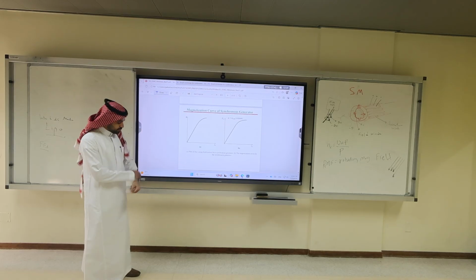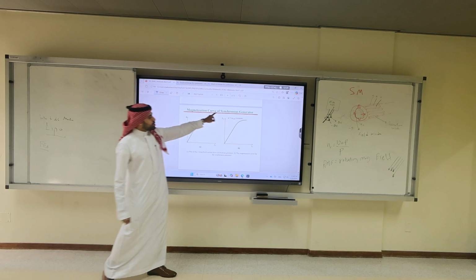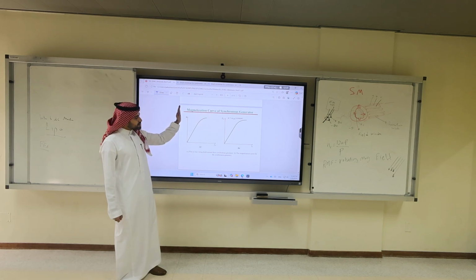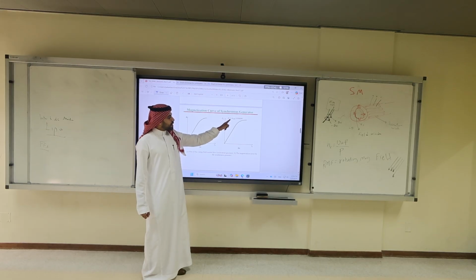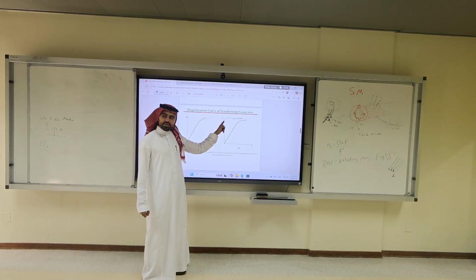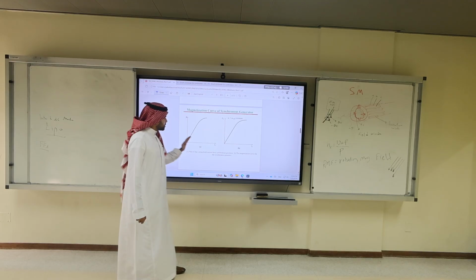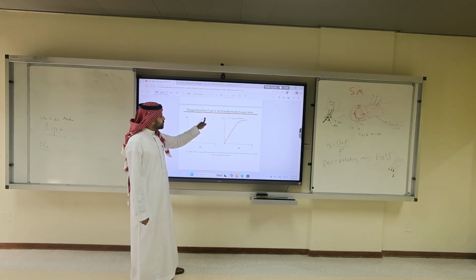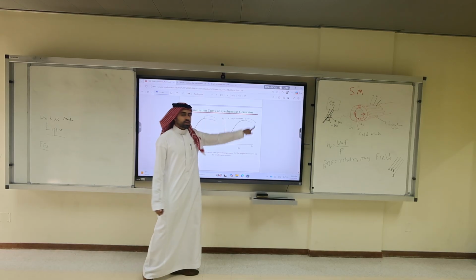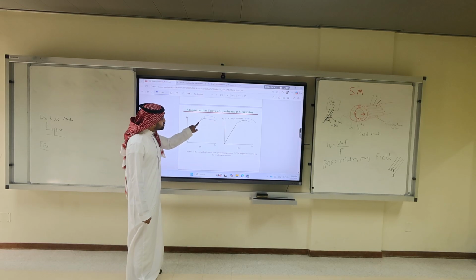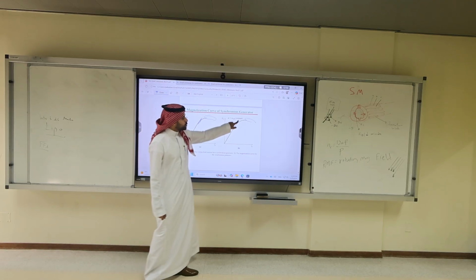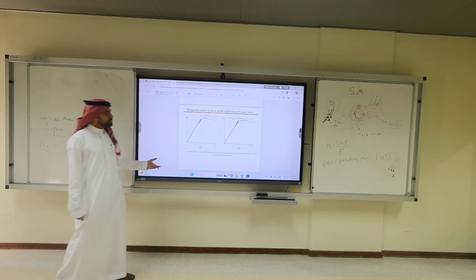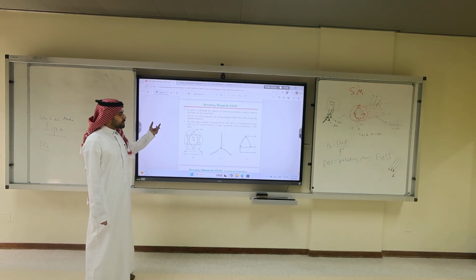And remember, the magnetization curve is if I increase the field current, I increase the flux. If I maintain the speed the same, I also increase the induced voltage. So it turns out that the relationship between them is linear, but I have a point of saturation. Do you want to operate at the saturation point? No. So you always operate just before the knee. You always operate just before the knee. That's a very important concept to remember from EE 360.